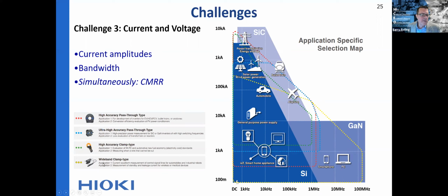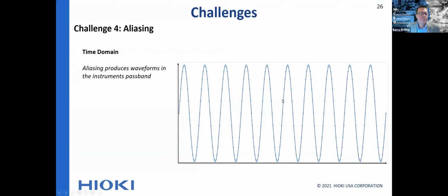These clamps tend to be for scopes. These are Hall effect, and these are all flux gate, zero flux. They're all zero flux. These are the zero flux gate, high accuracy CTs and clamps. So what's happening is we're getting more and more phone calls out here, and we have products out here. Now Michi will show you a couple of new CTs that fall out here into higher frequency and higher current both. So that's one of the challenges, and that's certainly a trend.